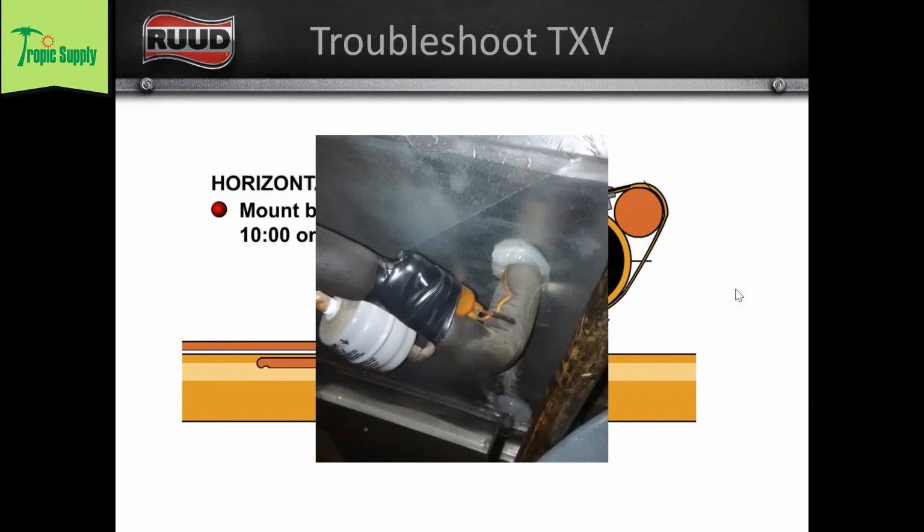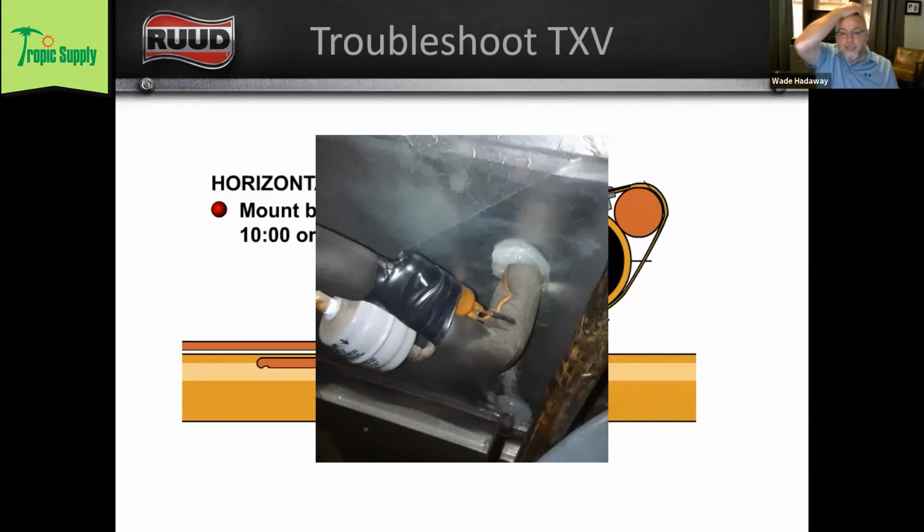And then what about location as far as distance? So as close to the external door of that coil as you can get it. Within 6 inches is great. I mean, if you take a turn, like in this example here, there's not enough room to put it right here because we've got a turn. So location wise or distance wise, this is probably fine, but I'd want to flip it 180 degrees. And you can't get too far because the transmission line or the capillary tube that comes out of that bulb is not really long.